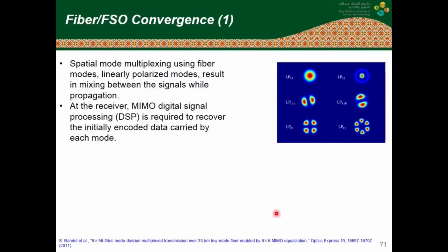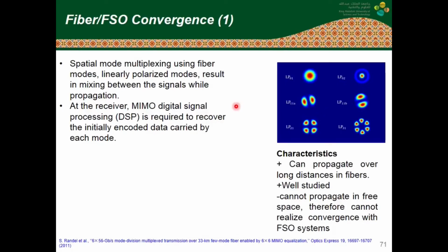Another potential of OAM structured light is ensuring fiber FSO convergence. But before showing you how, I would like to bring your attention to the commonly used mode set for spatial multiplexing in optical fibers. These modes are known as linearly polarized and can propagate over long distances and have been well studied in the literature. LP modes are approximate solutions to the wave equation, meaning they are not exact modes and are not orthogonal with each other,